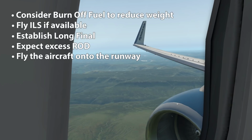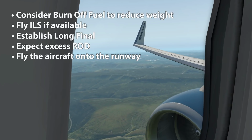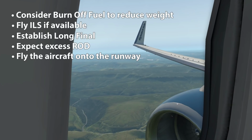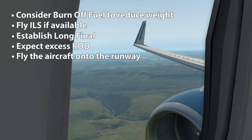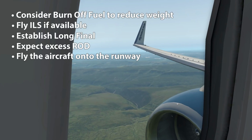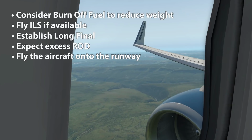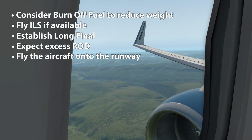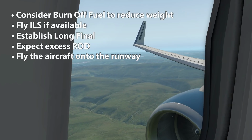It says fly the aircraft onto the runway. Pretty alarming, but the aircraft will have a huge tendency to float. It does with flap 15 single engine. So with the flaps up, if you overcompensate with the flare, you'll just go straight back into the air again. And Boeing simply says fly onto the runway and flare only enough to have an acceptable landing rate. So you don't want to fly it down at 1,000 feet per minute, obviously, but just a small flare, nice and firm, and right within the touchdown zone.